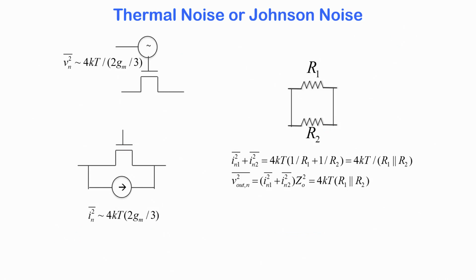Now in a MOSFET in conduction, you do have thermal noise when you have an inversion channel formation. Once the inversion layer is formed, you have a large number of electrons between the source and drain, and therefore the MOSFET has thermal noise through it. So when we talk about MOSFETs in circuits, we must take care of introducing the thermal noise if you are worried about the noise behavior.